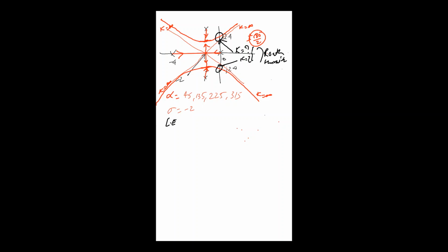The characteristic equation for this case, we are getting, is s to the power 4 plus 8s cube plus 36s square plus 80s plus K equal to 0. This is the characteristic equation. Make the Routh table. The highest power is s to the power 4. So this will be 1, 36, and this will be K. Here it will be 8 and 80.